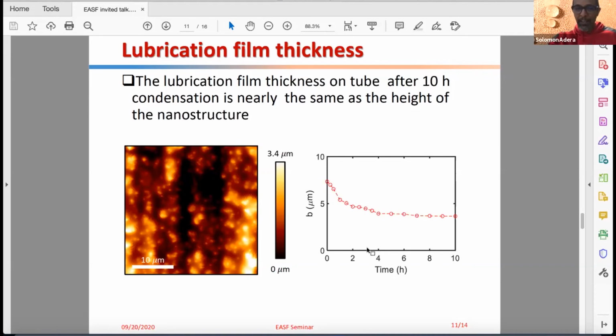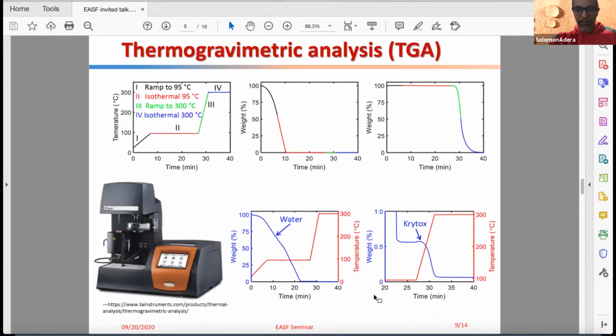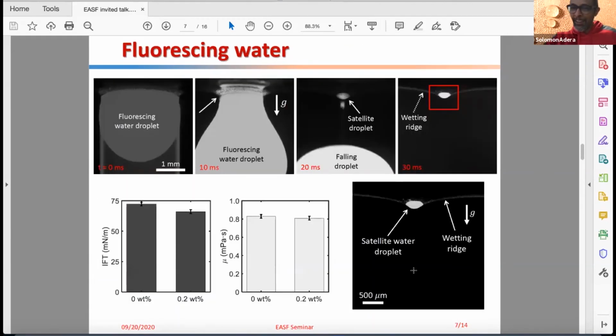Actually, this is a very insightful, good question. The satellite droplets are actually very useful. The reason is that the curvature shape by itself tells you that this is at lower pressure than ambient. So these satellite droplets create a large pressure difference at the oil ridge that holds the oil together. Therefore, they're very useful.